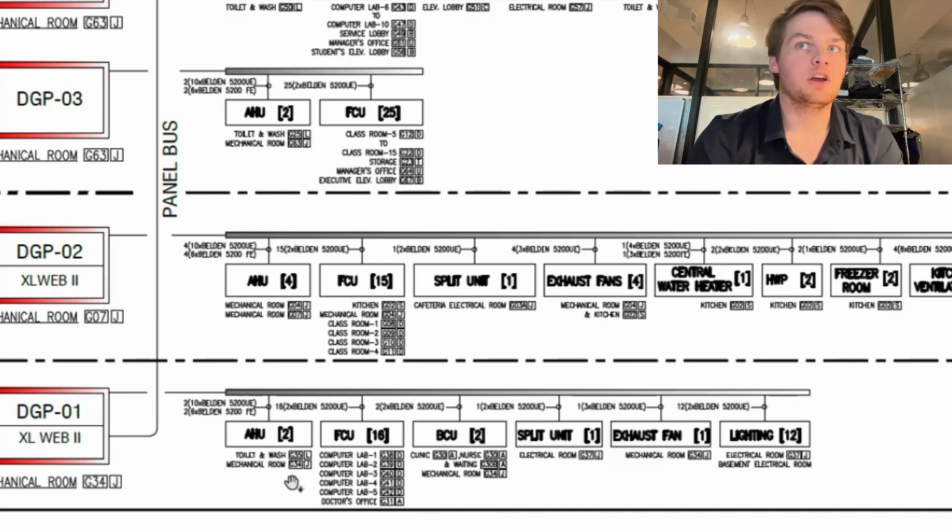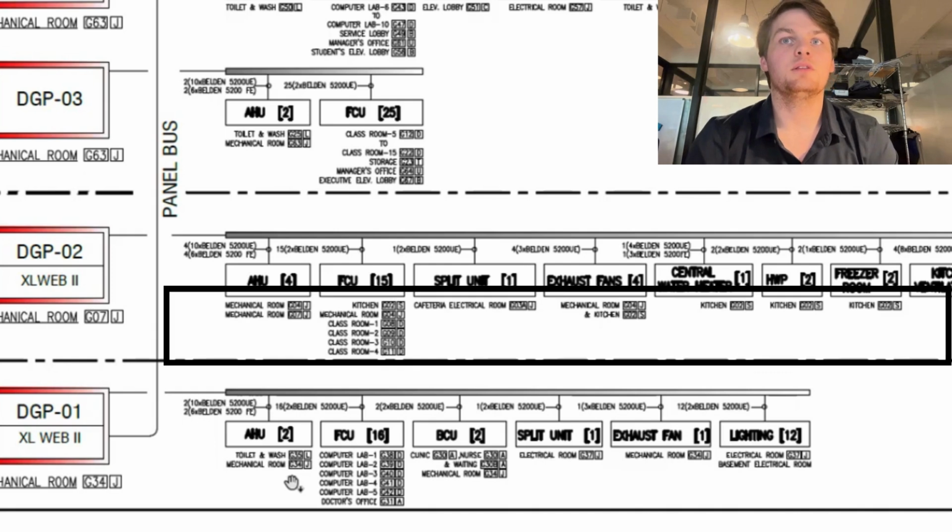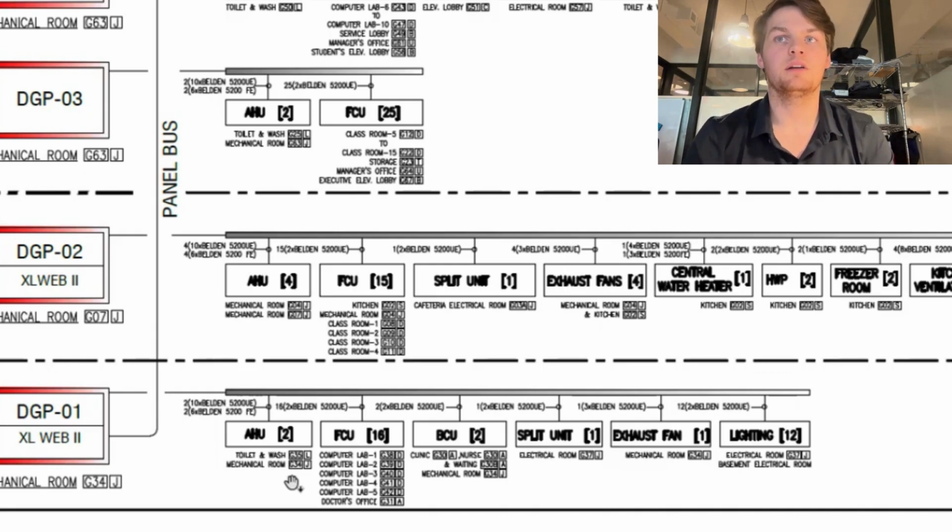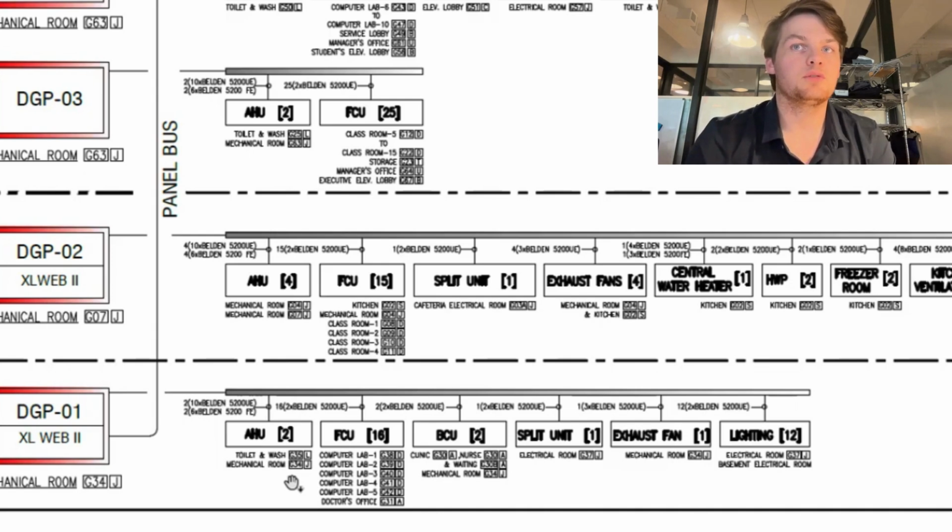A riser diagram is a visual representation of where these cables are going, including the floors, devices, and the type of wiring or connections. They're meant to help you understand the wiring layout between devices or endpoints by showing which devices are on which floors. This is especially useful for skyscrapers and other big buildings where not all floors will have the same systems.